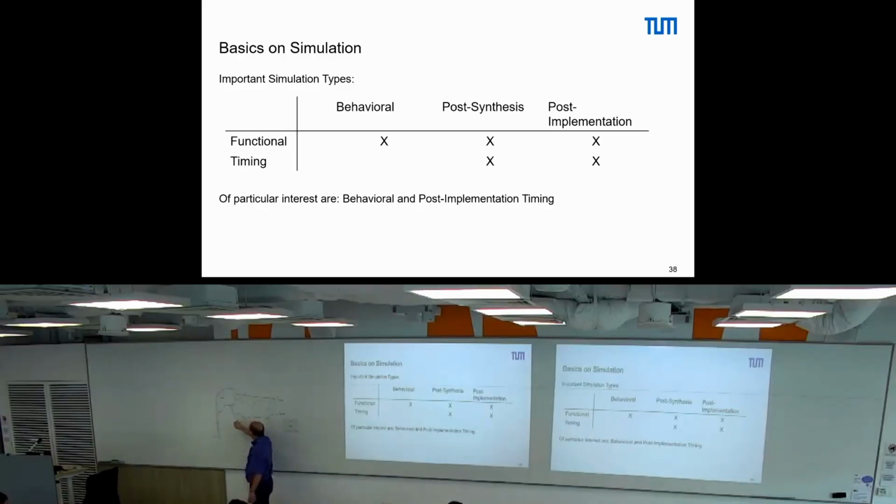So, the path through the inverter and through the OR takes, in the worst case, 0.9 plus 1.3, so 2.2. The path through the OR gate takes, in the worst case, 1.3. The path through the AND gate takes, in the worst case, 1.2. So the slowest path is obviously this one. The shortest path, we go for the minimum.